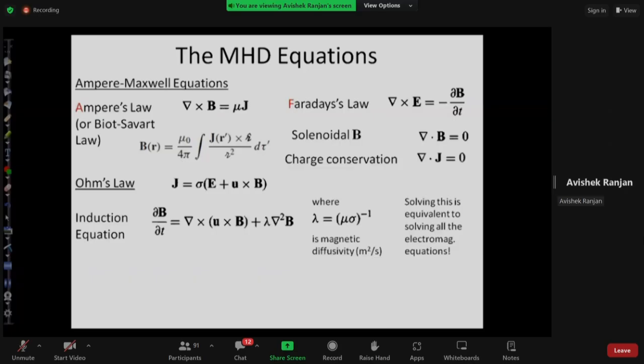But this equation also is a nonlinear equation. In case you have not noticed, there are two terms, u dot grad of B and B dot grad of U. Both could be nonlinear. So it's a complex equation just like Navier-Stokes, so not always easy to solve. Especially if you're solving it in conjunction with Navier-Stokes, there are a lot of variables involved. So it is this Lorentz force which essentially is the term important to initiate flow or accelerate the flow or retard the flow, depending on its sign.